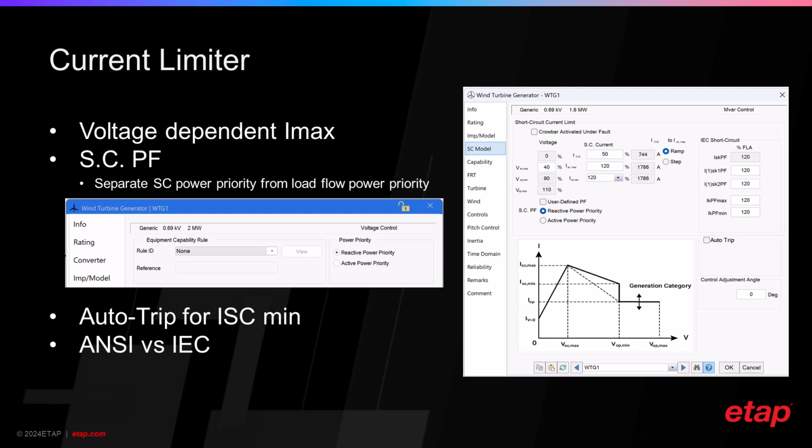It says that the moment voltage drops below, let's say in this case, 0.9 per unit in positive sequence or negative sequence, above 10%, there would be a flag that would be set, and then this curve becomes continuous.